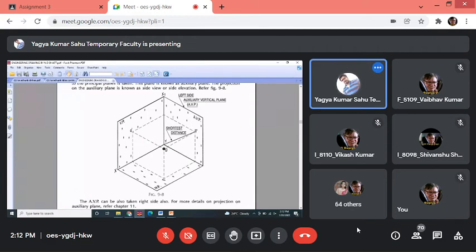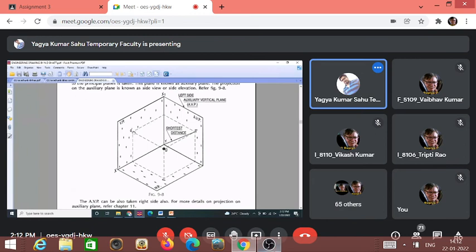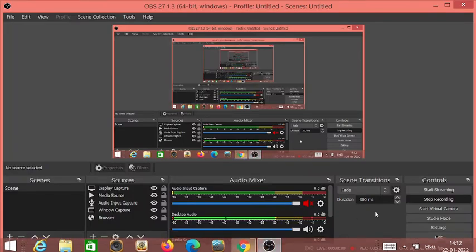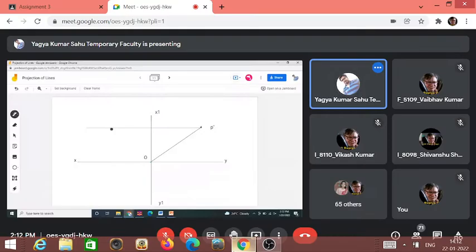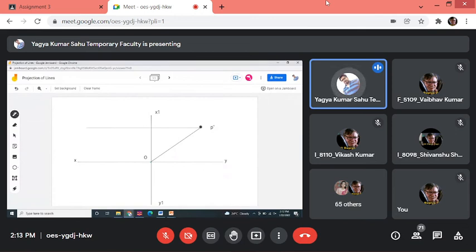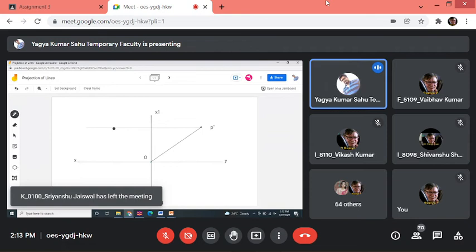And you can say these two projector lines will form a single projector line, which I have already drawn like this. Means in this projector line we will get Q dash. If you take the point P, you write P dash, and in this example, we have taken that point Q. So what about the P dash? P dash you will get on this particular projector line. In this same projector line you will get P dash, the front view of P. Yes or no?